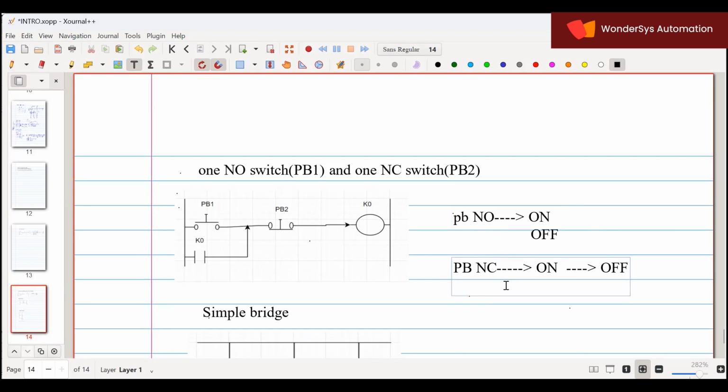So this is not in the ladder condition. This works, the switching operation itself is like this. Okay. Now, how are you going to write the ladder for that? So now I have to represent this operation in ladder symbol. Which one should I be using? NC itself.